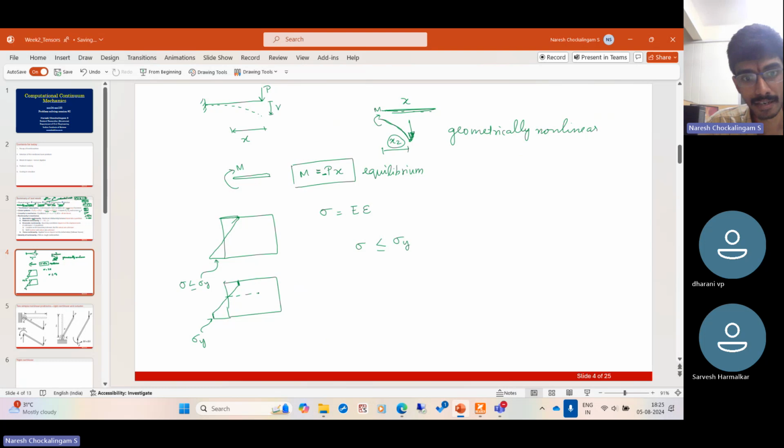How do you express the stress strain behavior? So here, as you increase the strain up to a certain point, the stress increases proportionally. And beyond that point, assuming there is no hardening, you have a yield stress. So this is nonlinear. It consists of two linear segments, but in general, this is nonlinear. So in this region, you have the elastic modulus as E, and here the elastic modulus is actually 0. At constant stress, you can have indefinite straining.